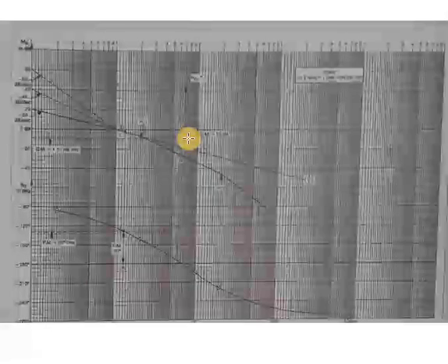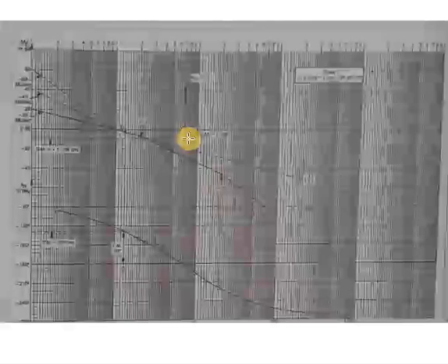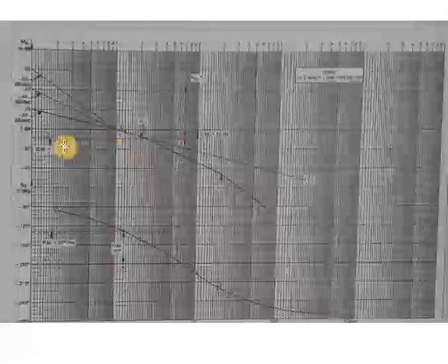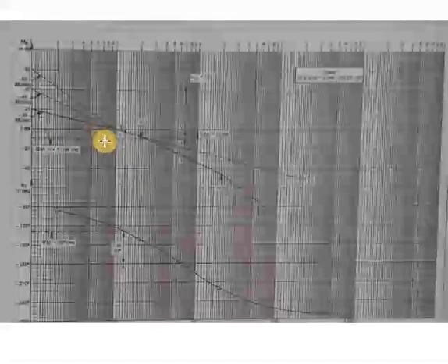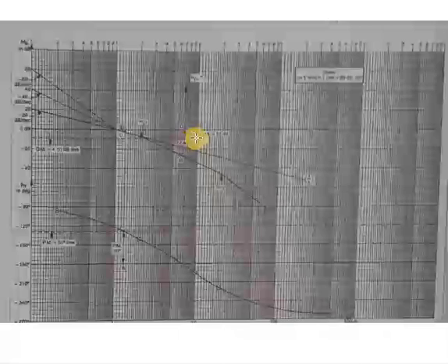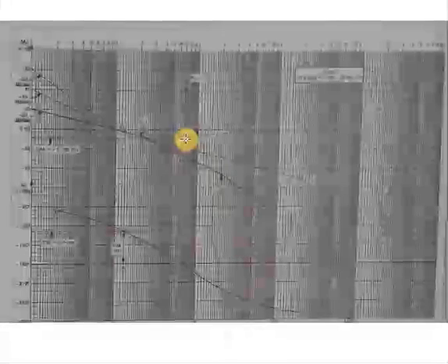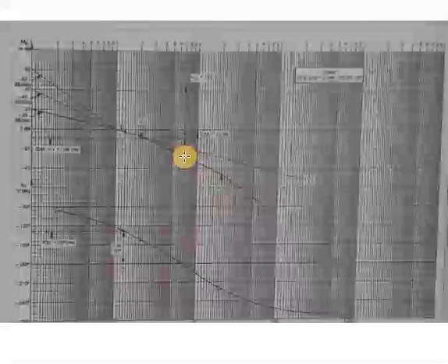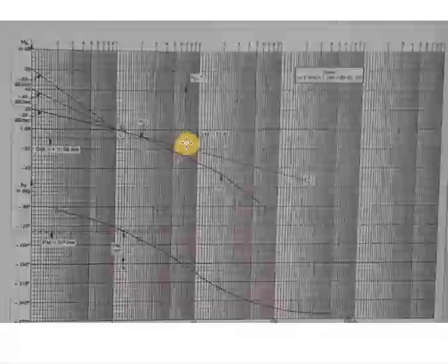But here we should have the specific gain margin as 10 dB. So at 10 dB you draw a reference line and measure the distance between this 10 dB line and this magnitude plot, that is AB. This much shift is required to have the system gain margin as 10 dB.